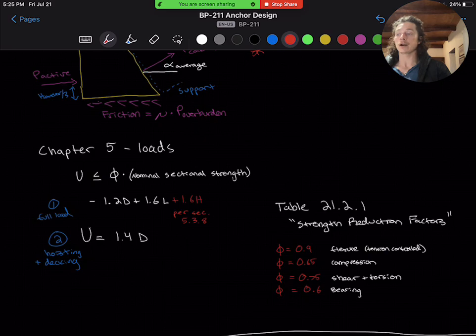And notice that we are going to ignore serviceability design here. Unlike in the towers, because the anchors are buried into the ramp, if cracking occurs and the anchor beam begins to slightly deflect, it will be supported by the ramp fill and the overburden. So as long as the strength requirements are met, we will consider this to be sufficient.